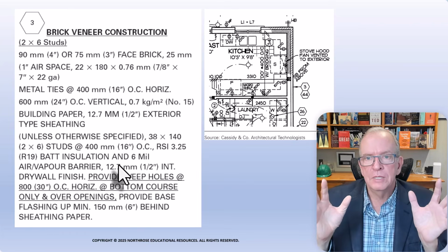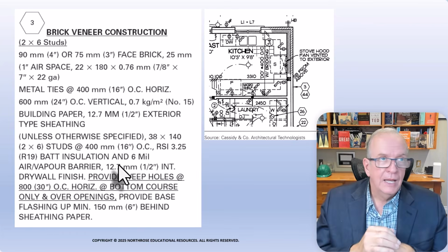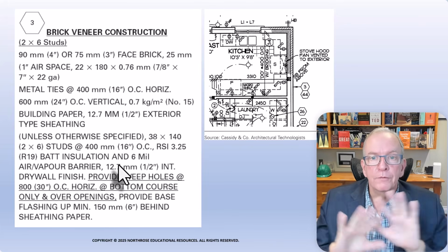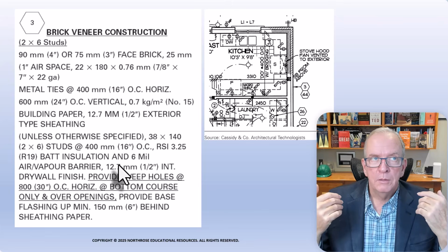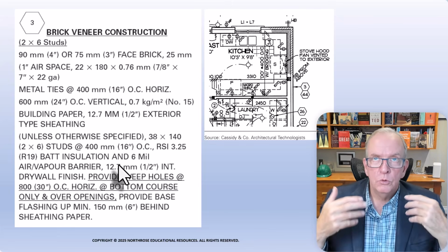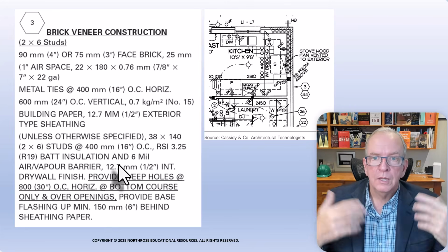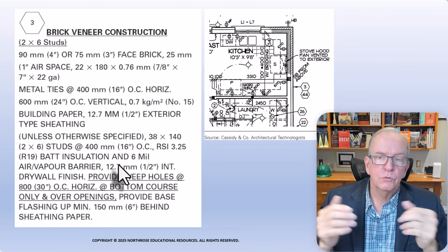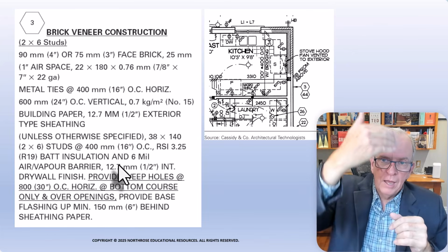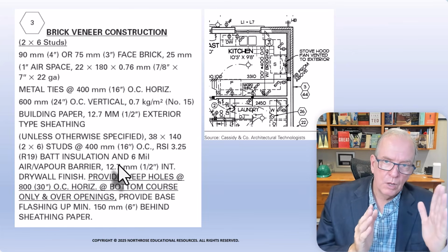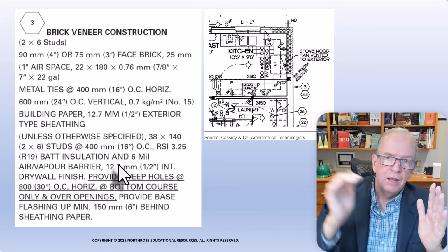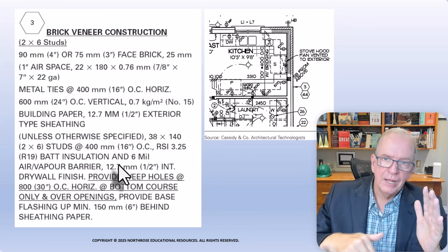A big building science principle is that there's no such thing as a perfect barrier. You're never going to perfectly seal the outside. So the better the system is at being able to dry itself out, the fewer problems you have. Brick veneer is a really good system in that there is this airspace. We have a weather barrier on the inside side of the airspace. And if any moisture gets in, it can get out or it'll dry out.